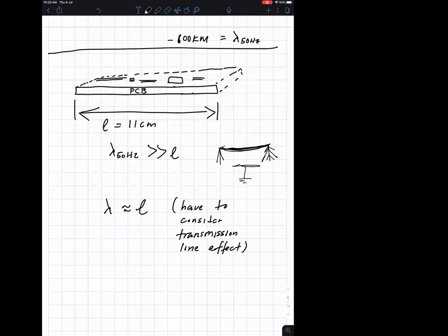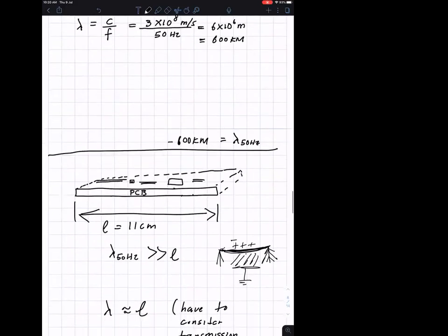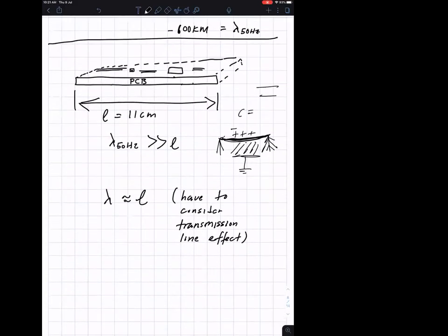So when it was raining, the dielectric may have changed, because of the space between. This is ground, and this is maybe positive or negative, swinging, right? Negative, positive, AC. Maybe when it's positive, it can jump. So this is your dielectric, air. If you look at the capacitance formula, if there's a separated plate with an area and a separation D, the capacitance is area times dielectric, the material in between the plates.